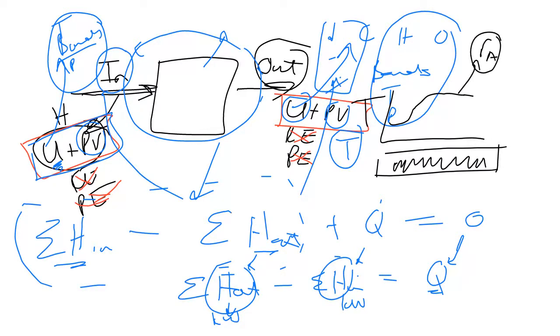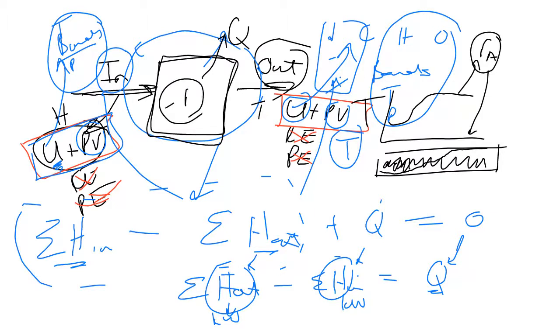So we are not only interested in the duty that Aspen can calculate for us happily, but when you design reactors, Aspen cannot help you because you need the temperature profile through your plug flow reactor in order to compensate for the fact that I don't have a constant rate here. And in order to size my reactor, you specify the temperature, calculate the duty, but the sizing of the reactor and what is the rate that must be available will be up to you.